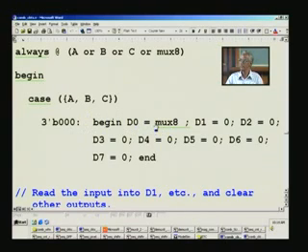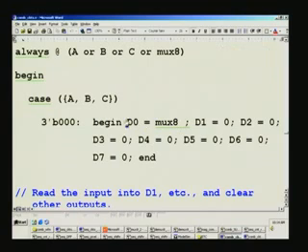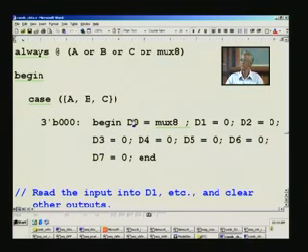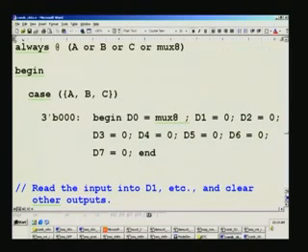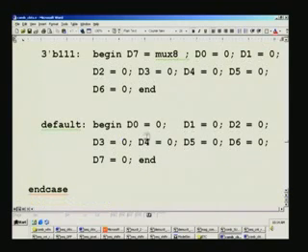So what we put in as input for mux 8, namely I0 through I7, we will get the corresponding D0 through D7 as the output, which will be the very same as the I0 through I7 that we have. And we have also seen a default condition towards the end, which resets all the outputs, because in the course of the circuit working you may encounter X in any of the bit positions, or even Z, which is indicative of a tri-state condition.